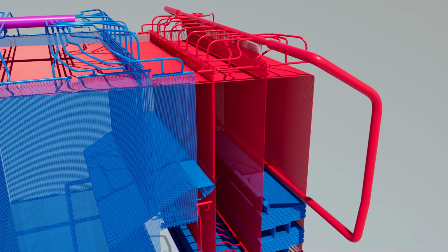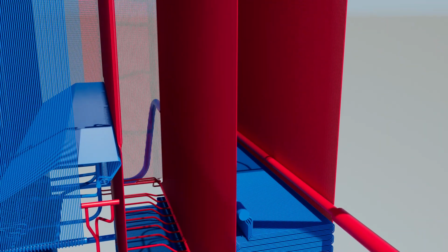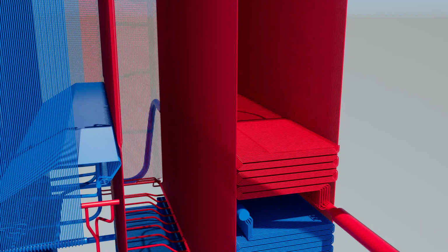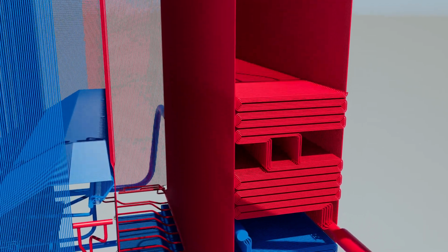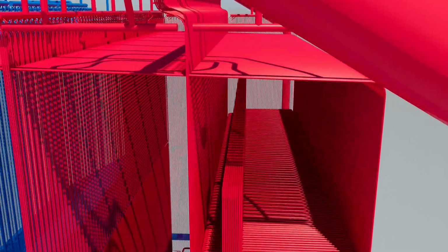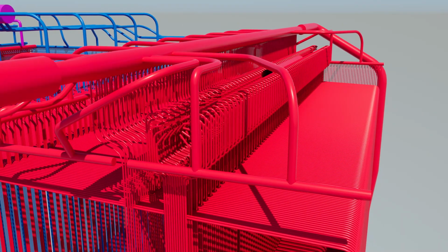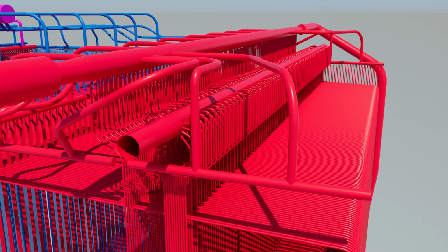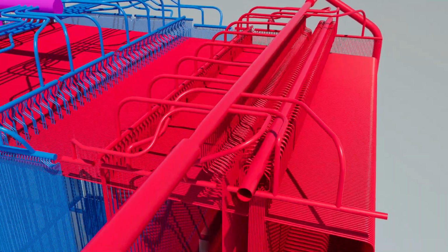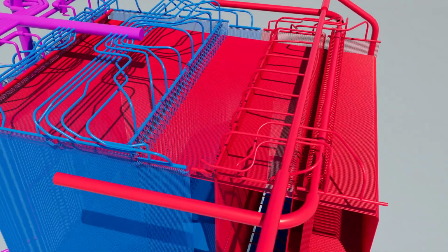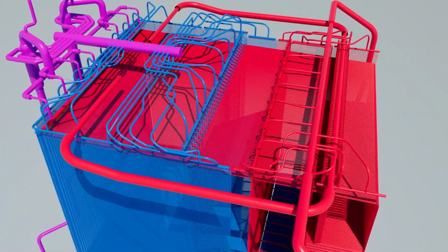The primary superheater is located in the rear path of the HRA section. The primary superheater consists of the horizontal loop elements arranged across the boiler's width, the inlet and the outlet headers. The primary superheater is connected to the secondary superheater by the connecting pipe.